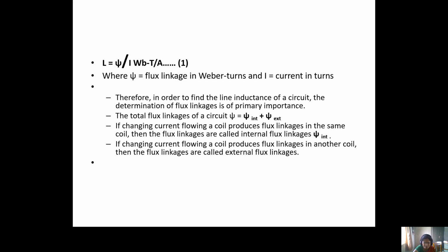Therefore, in order to find the line inductance of a circuit, the determination of the flux linkages is of primary importance. Whenever you have to find the inductance value L, it is important first to find the flux linkages.